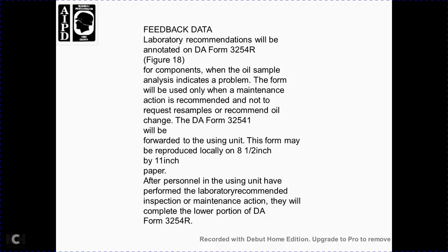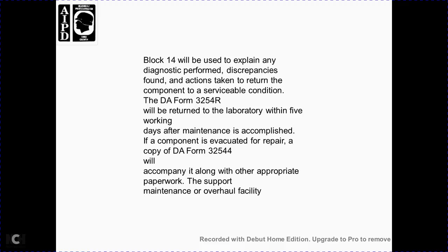The personnel in the using unit that have performed the laboratory recommended inspection or maintenance actions will complete the lower portion of the DA Form 3254-R. Block 14 will be used to explain the diagnostic performance and discrepancies found, and the actions returning the component to serviceable condition. The DA Form 3254 will be returned to the laboratory within 5 working days with the maintenance accomplished.